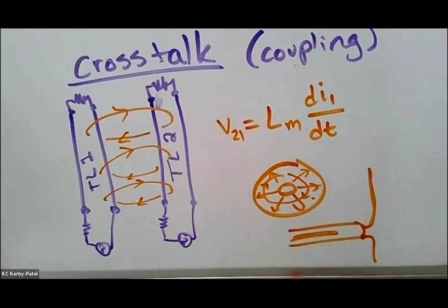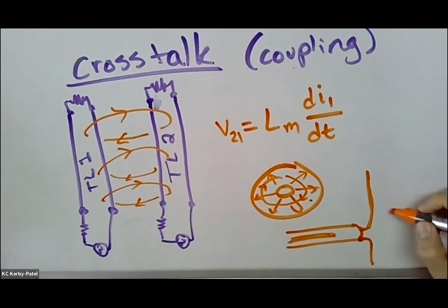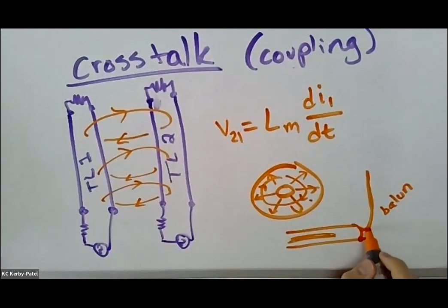This is a situation that as an antenna person, you have to mitigate a lot. So I think about it pretty frequently. And it introduces the whole concept of a balun, which is for transitioning between something with a ground and something that's supposed to be operated in a balanced way with a plus voltage on one end and an equal and opposite minus voltage on the other end.